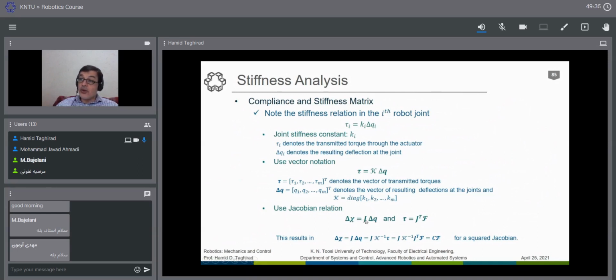Of course, we talked about the Jacobian as the velocities dx/dt related to dq/dt. But since they are very, very small, delta q like dq, we can remove the dt in the denominator and see that these are related to each other, as we consider for the virtual work approach.